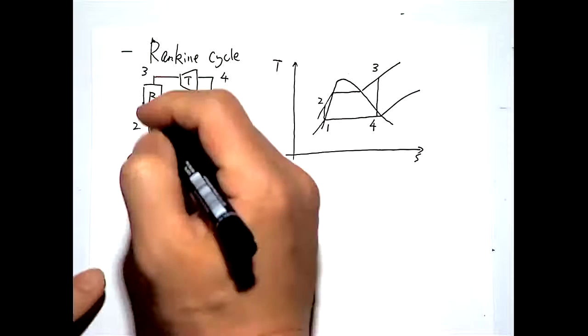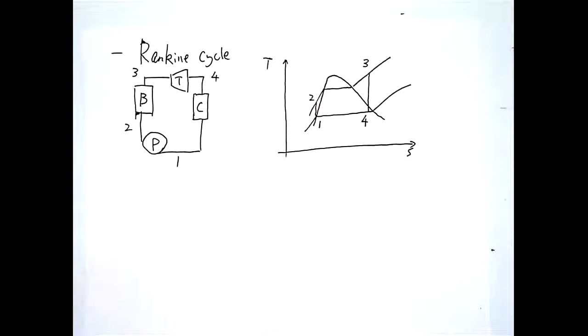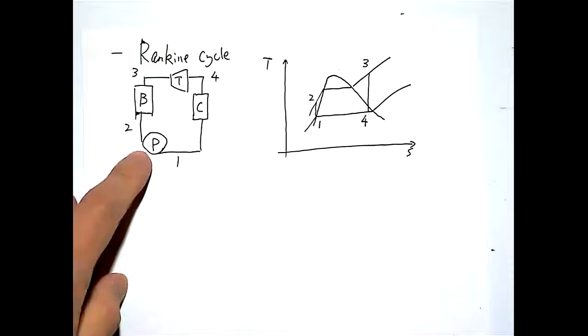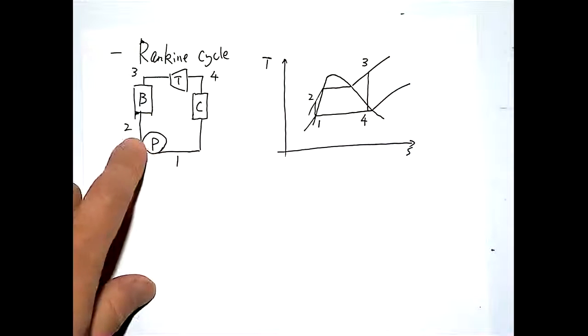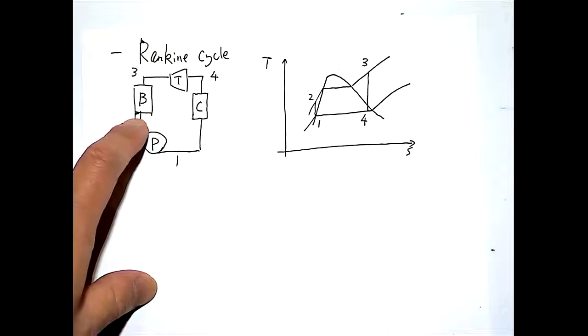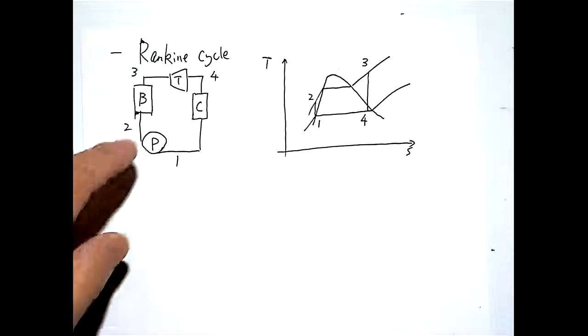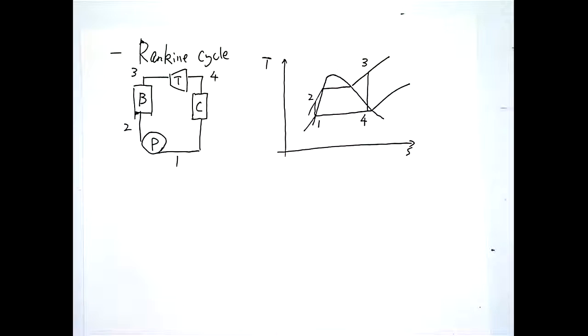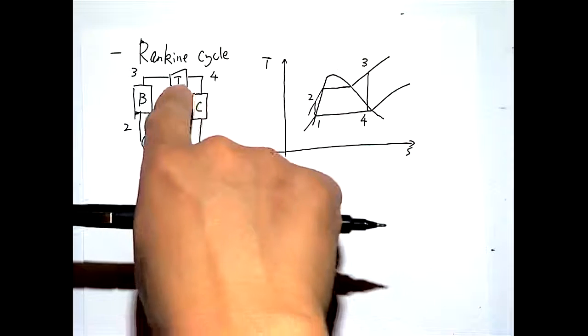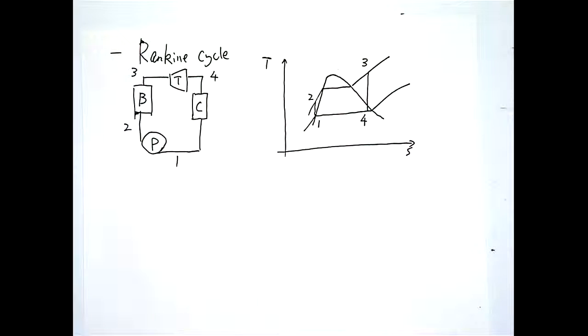So in this cycle, we have four components again, starting with a pump, which is pumping liquid water and raises the pressure into this boiler. Boiler essentially is a device where you can add heat into it, and that happens at high pressure and high temperature as well. And then the pressure is high, you need a device to drop the pressure, right? You're using the steam turbine. Turbine, again, is similar to a gas turbine. We assume it's an isentropic process. And when the pressure is reduced, the temperature is dropped, then you can output the turbine work.